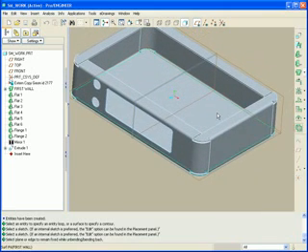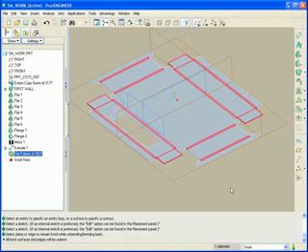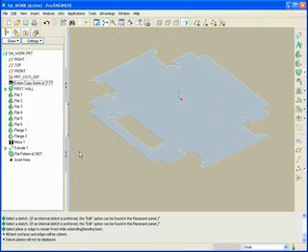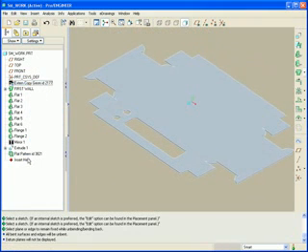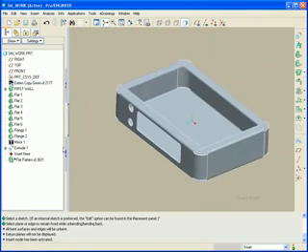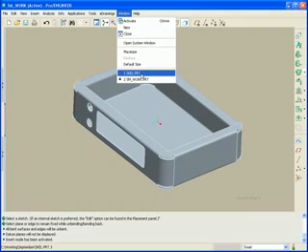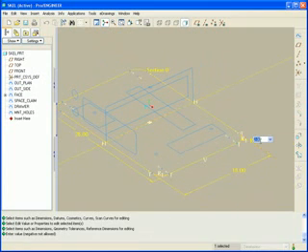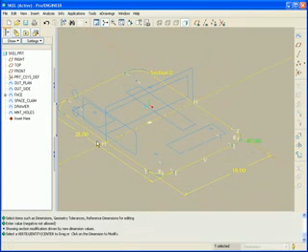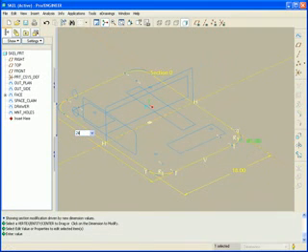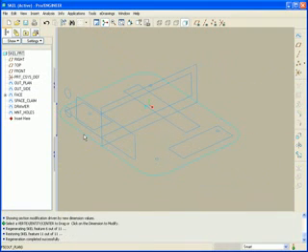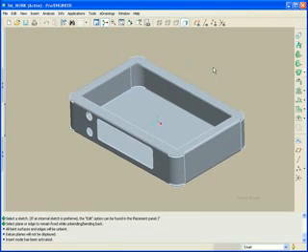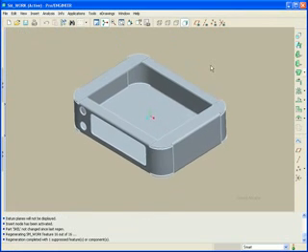Let's ask for a flat pattern real quick. Boom. Turn off the planes, and you might want to hide your copy geom. So there is the sheet metal part. Now if I go back to the skeleton, and some changes might have happened here. Perhaps maybe this is supposed to be 3, and maybe let's take this one to 24. Control G to regenerate. My model now, Control G, easily updated.